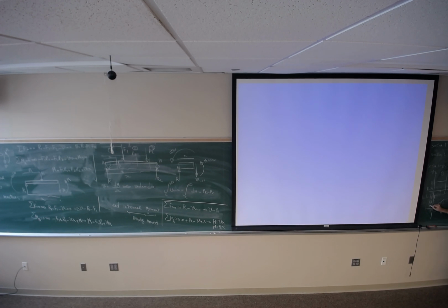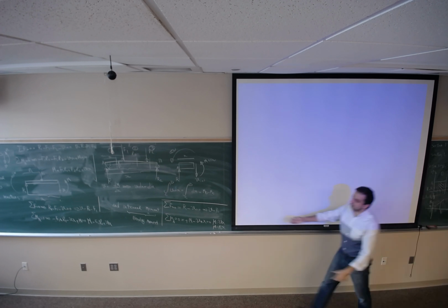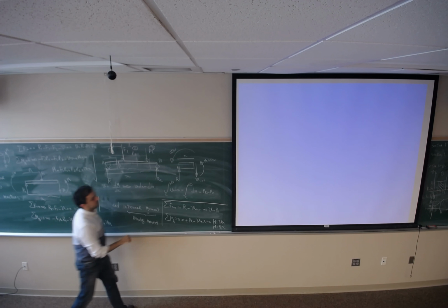The moment at point C, the moment at point D. The difference between the moments of these 2 points, MD minus MC, is going to be the area surrounded by the shear force, the integration of V dx from point C to D. So whatever this area is, it is going to give you the difference between the moments of point D and C.